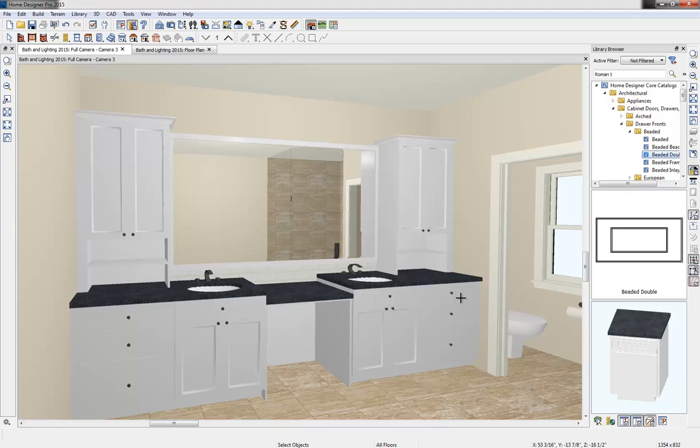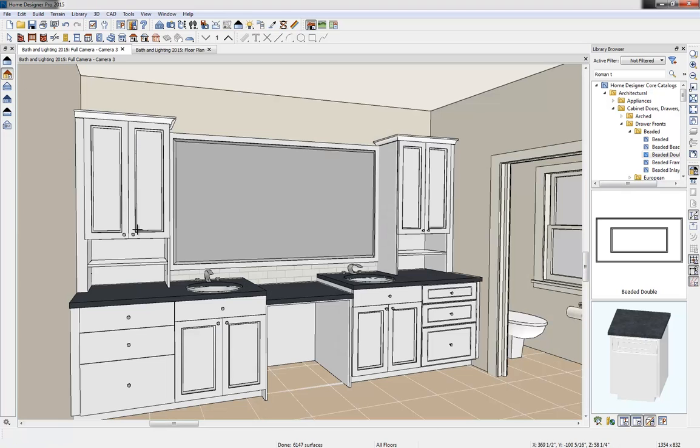So once you have that selected, just single click right on those drawers on the fronts there, and it's going to change. Let me get into a different view. It might show a little bit better here. So under my rendering techniques, I'm going to select our vector view. So that kind of changes, and you can really notice the different style that we have here compared to that flat panel that was originally on there. So let's just continue and just single click and drop all of those new drawer fronts on.